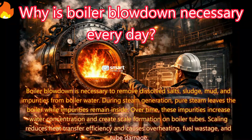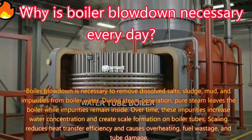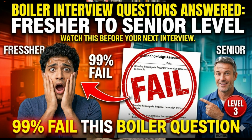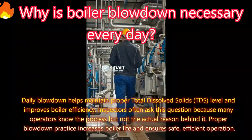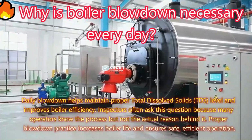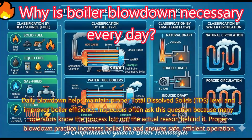Scaling reduces heat transfer efficiency and causes overheating, fuel wastage, and tube damage. Daily blowdown helps maintain proper total dissolved solids (TDS) level and improves boiler efficiency. Inspectors often ask this question because many operators know the process but not the actual reason behind it. Proper blowdown practice increases boiler life and ensures safe, efficient operation.